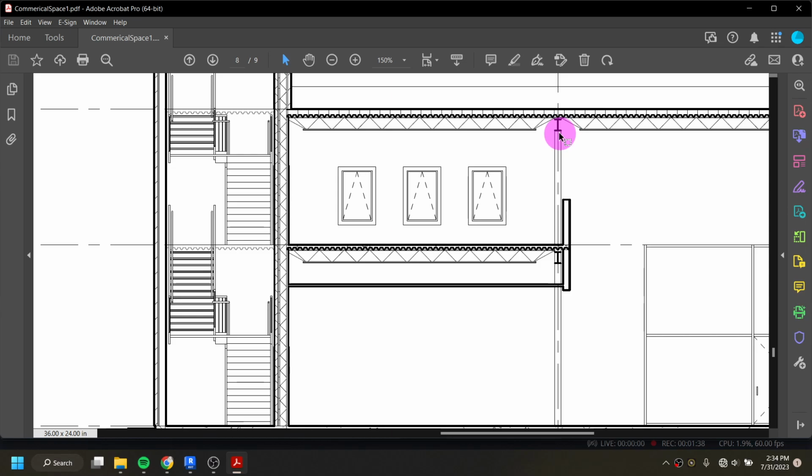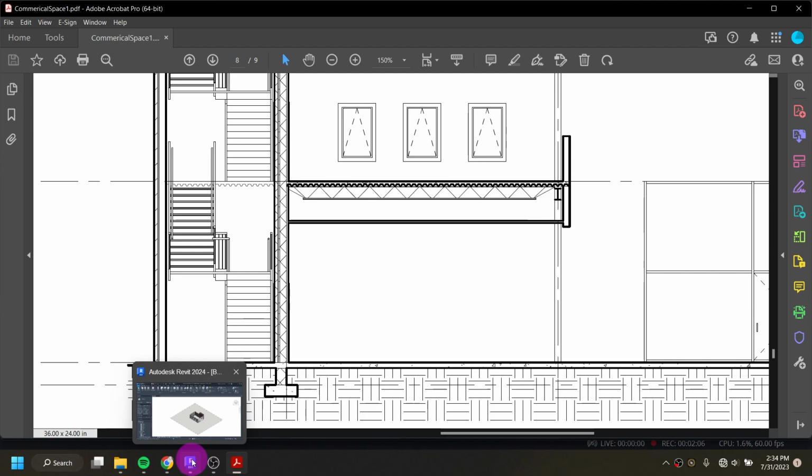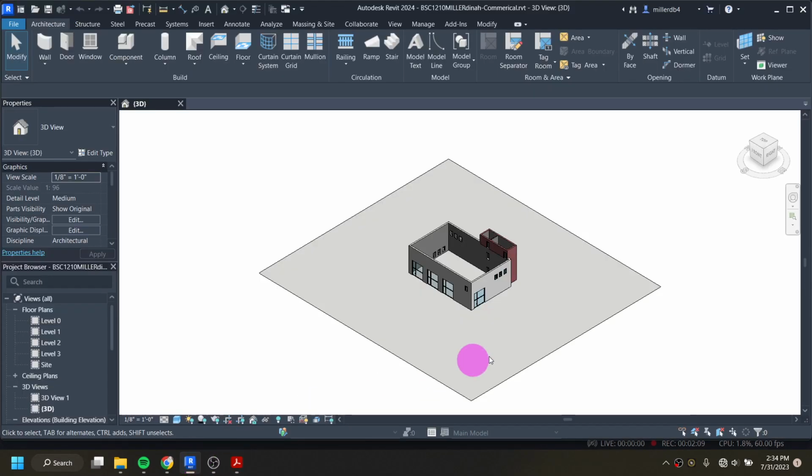I will tell you the amounts just by looking at the finished product that I have on another computer here, but I'm not making numbers up as I go. I'm just doing amounts based on how thick this floor is and then this beam as well that's holding it up. So when I'm coming up with these offset amounts, just know that I'm taking them from the measurements that are based on our material thicknesses. But we'll start off with that knee wall and then we'll work on our floors.